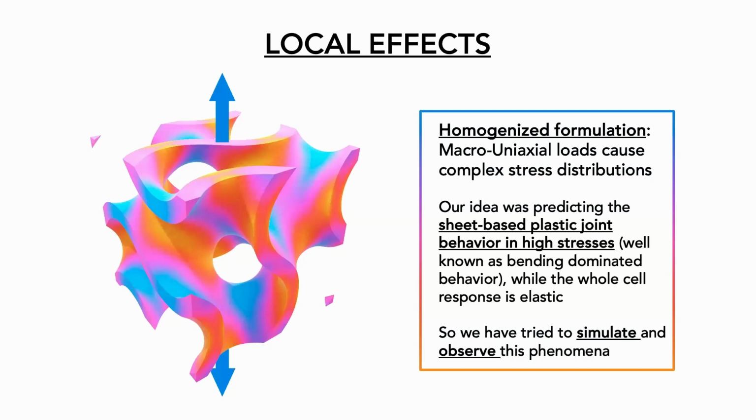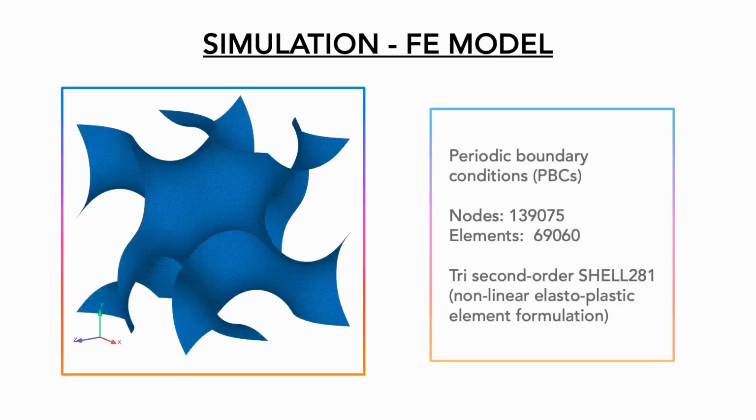The fact is, this localized stress can be seen as a plastic joint, and then we have an elastic global behavior and a local plastic behavior that can be useful for something, as you will see in the conclusion, obviously. So the point is to simulate those kinds of things and also observe them in some way, but with the field and not a point value. So the DIC was fundamental for that.